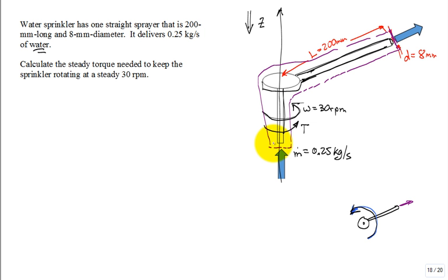And closes and cuts where the fluid cuts at two places, coming in and going out. Now, that control volume has an axis, and that control volume is rotating with omega around that axis. True? So you could think of the control volume as cut here, come back, go there. And that control volume does rotate with the same speed. All right. Let's apply our angular momentum equation.